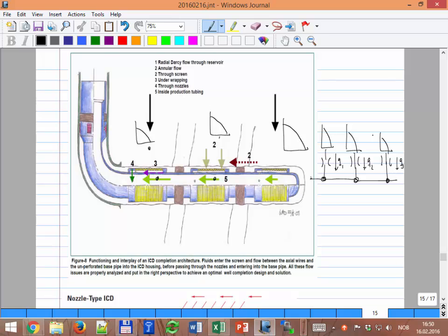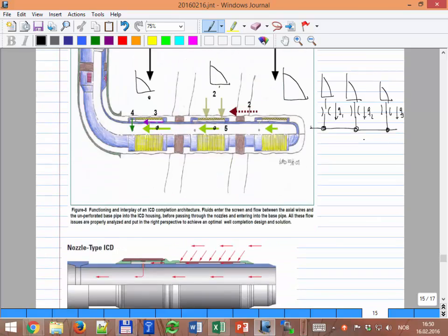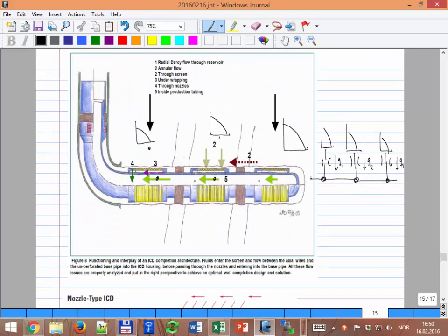Then we have seen this part about how you split rates. That is actually very important, and you have different methods. I told you that the network is usually a better approach because you're analyzing everything that happens downstream of the well. When you do it with the reservoir simulator, you have to use a very good value of PWF minimum that represents the back pressure of the network. And finally, we saw that we also have downhole networks, and we have to deal with that. So that's another complexity you have to be aware of.